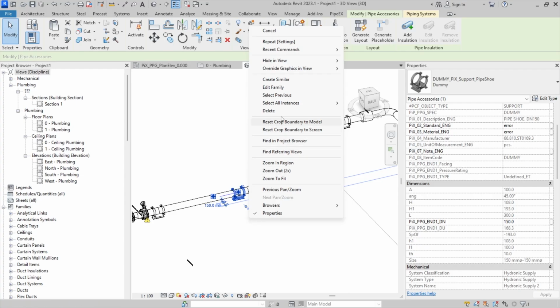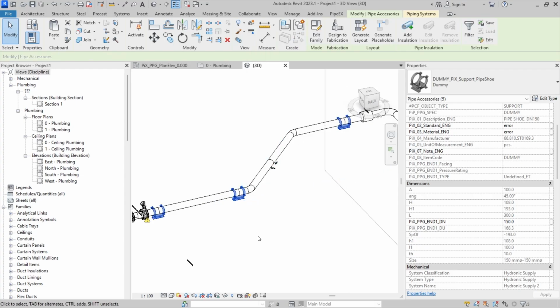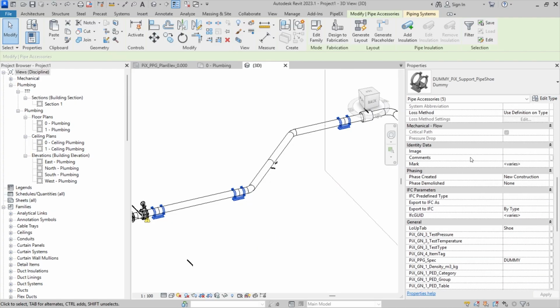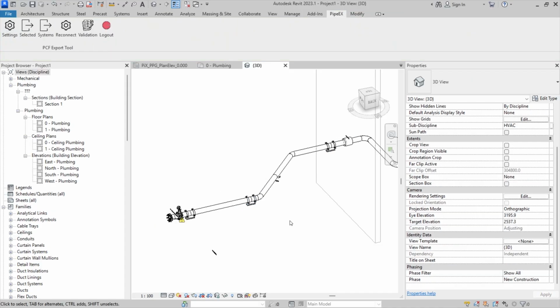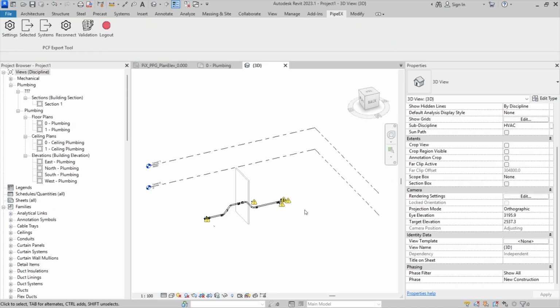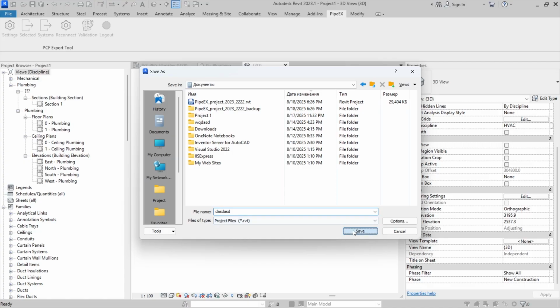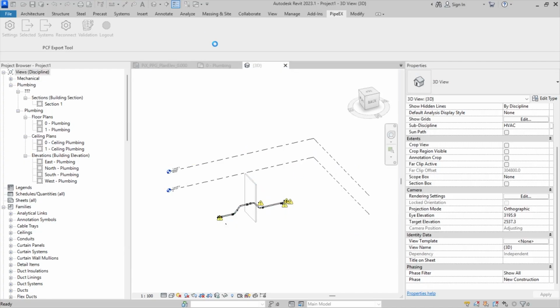So I'm just going to select all of them as visible in view, and I will assign them the same tag, because let's say they will use the same type of secondary steel support. So it will be ST001. And that's it. I will call it, doesn't matter how, abracadabra.